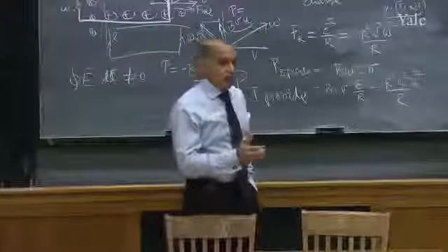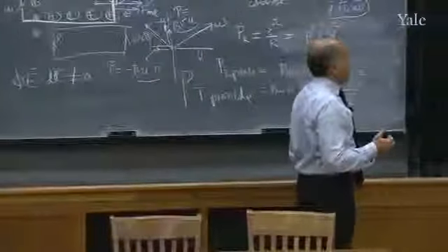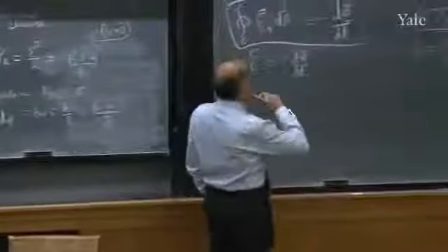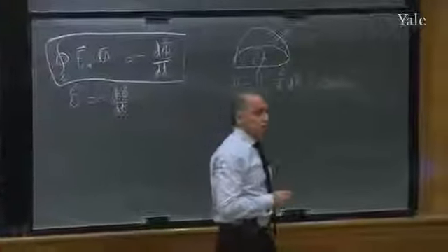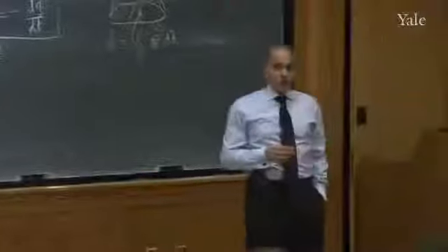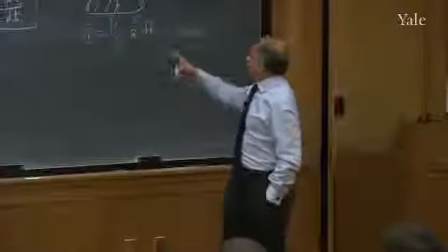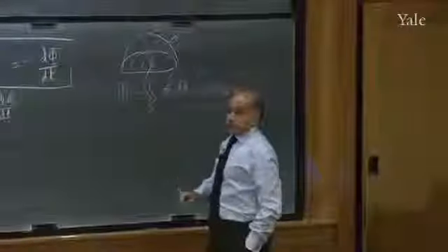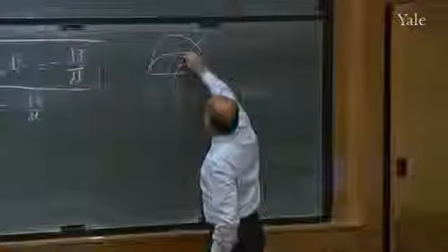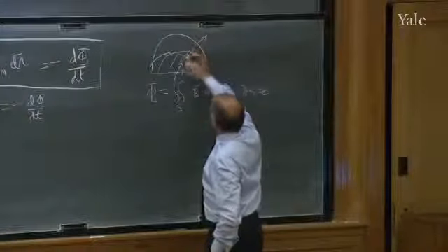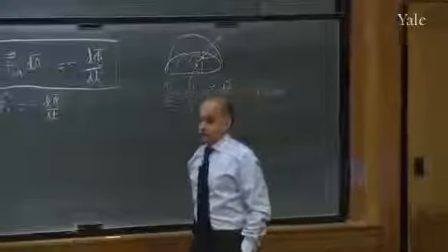So whenever you have these laws where a surface is invoked and it's ambiguous and not defined by the perimeter, the answer is it doesn't matter which surface. The reason is that field lines don't stop and end. Therefore, whatever enters this surface has to leave this. If you had magnetic monopoles, lines can enter this and terminate on a negative monopole, then of course it won't be true, but you don't have them.